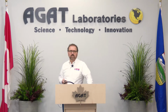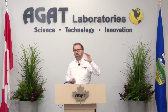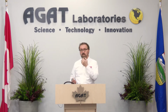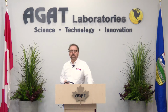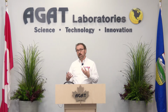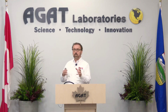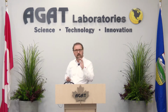An important factor when you're dealing with any type of remediation product is to understand its purity. So we've all heard of industrial grade, commercial grade, maybe medical grade or research grade. The purity increases across those four that I've mentioned, as does cost usually, right? So when you're dealing with any kind of remediation product, make sure it's free of any impurities or byproducts of concern, or if there's constituents associated with it, that after the application you actually monitor before and after. Get your baseline, like if you're using a sodium permanganate or something, make sure that you don't have more sodium than you want pre to post while you're applying that, because you may solve your problem but have a lingering issue. So just be mindful of that.